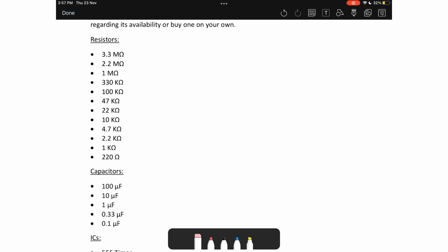I'm going to use the parts list to find out what is the resistance. So I need 4.54 mega ohm, and I can use for that 2.2 mega ohm plus 2.2 mega ohm, which is 4.4 mega ohm. Since I need 4.5, I have around 100k, maybe 150k missing kilo ohm.